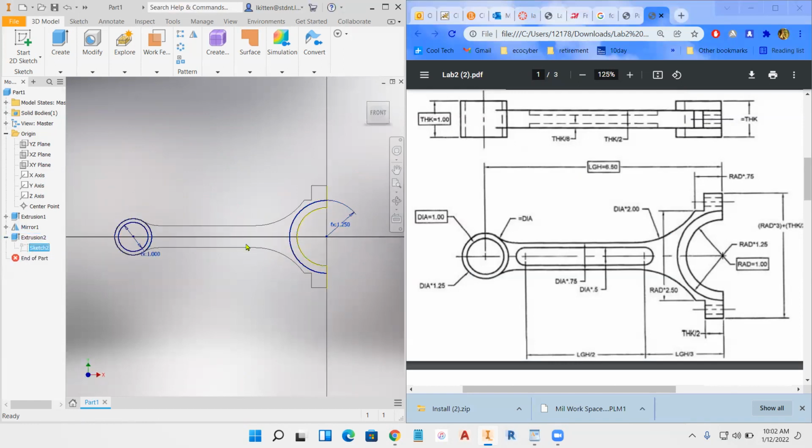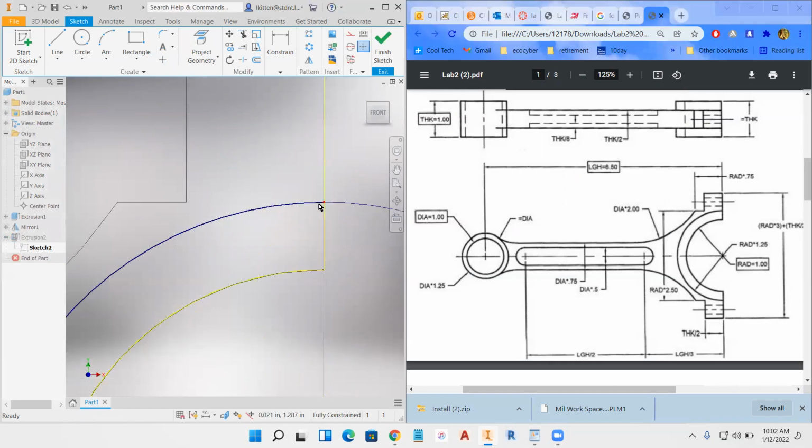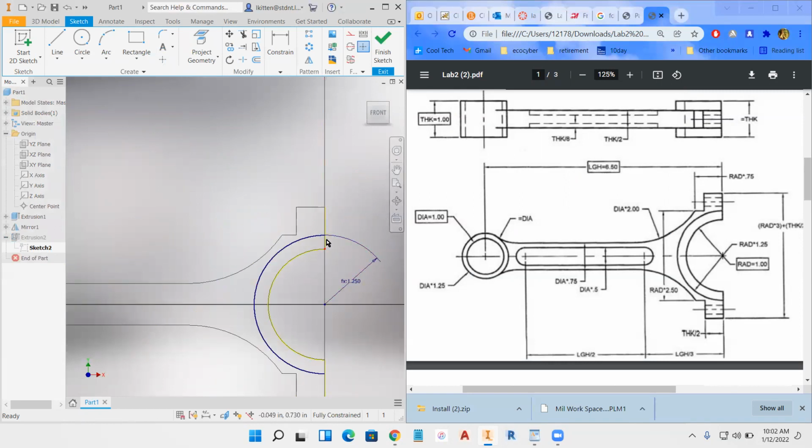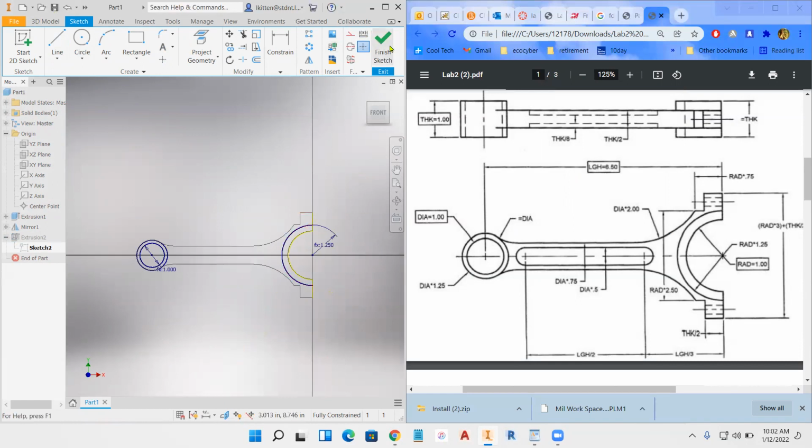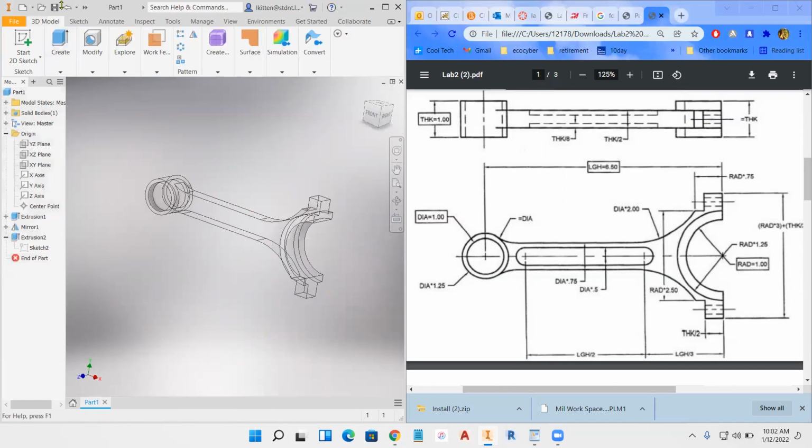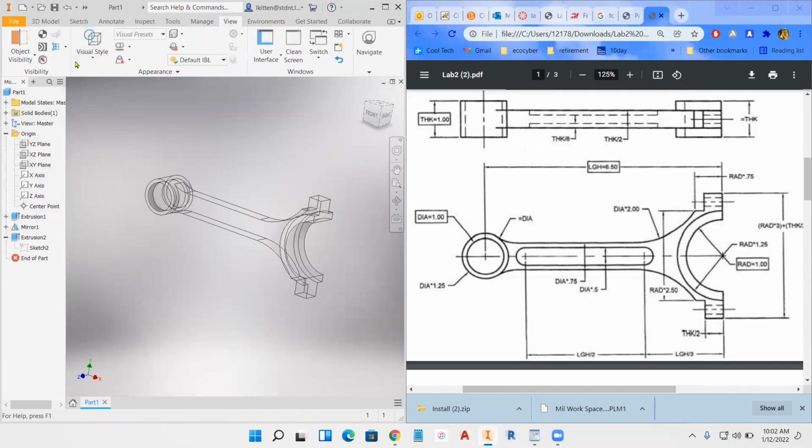If that still doesn't work, the other option is, in that sketch, a lot of times it doesn't like projected geometry. So just redraw over the top of that stuff and make sure it's fully constrained. Either make it equal, or like I did with that other one, if you have to. Usually you can just draw over the lines and arcs, going from there to there, and as long as it stays fully constrained, you're good. Do the other one down here and draw this arc. We didn't have to do that, so I'm not going to worry about it, but it's the foolproof way. Finish sketch. I don't like working with hidden lines in 3D, so I'm going to turn that back off to shaded with edges.